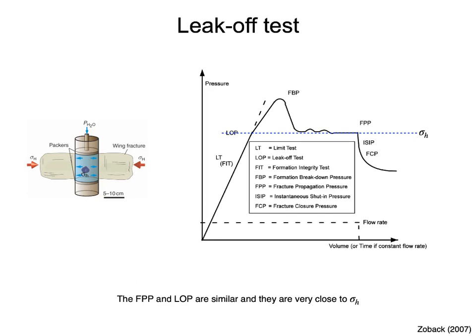Therefore, from borehole breakouts, we can estimate the orientation of the horizontal stresses. And from leak-off tests, we can estimate the magnitude of sigma h. The magnitude of sigma capital H, however, is more uncertain.